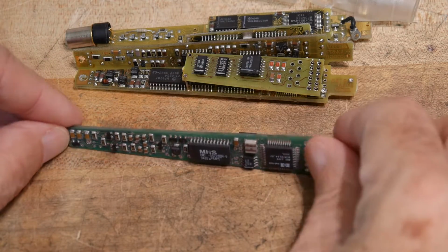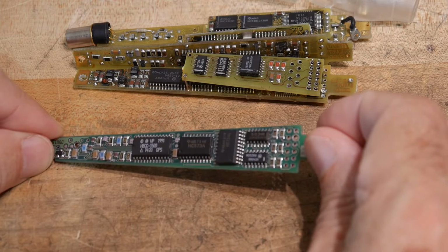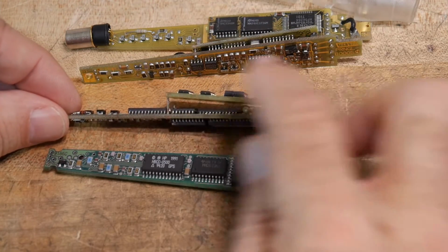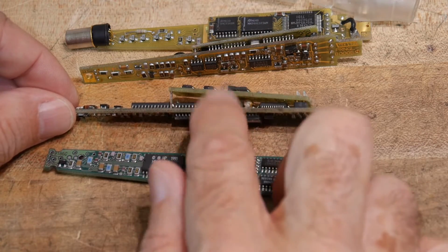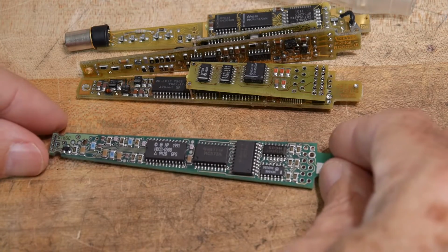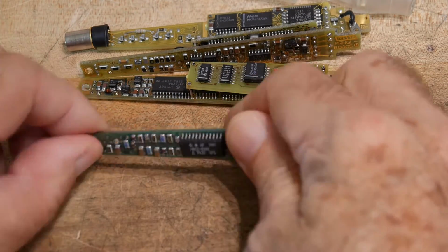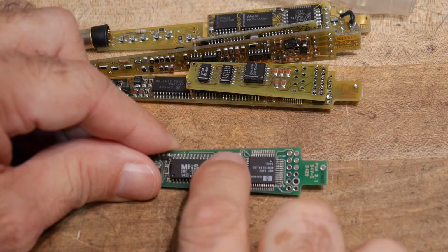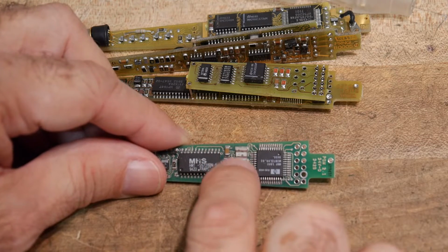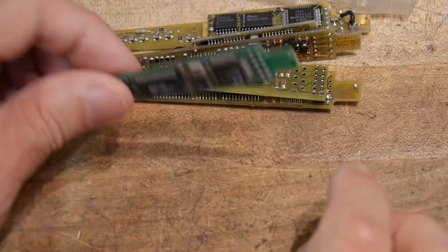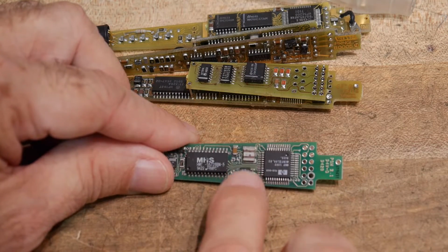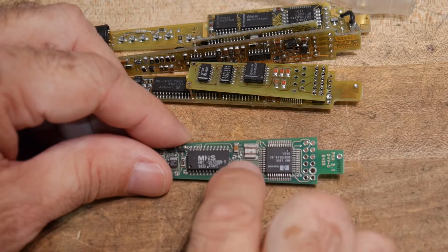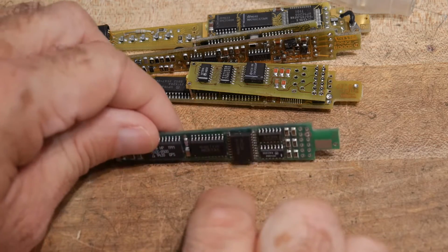So here's another generation. This is pretty nice. So this has the same functionality as this. We've managed to take all of the circuitry that was on two PC boards and put it all onto one PC board. Again, the front half of it is analog with a custom chip, and the back half is all digital stuff. The microprocessor, you see, we've gone to a ceramic resonator instead of crystals, much more rugged. The EEPROM is now available in a smaller package, so we're able to reduce that. This is a RAM chip.